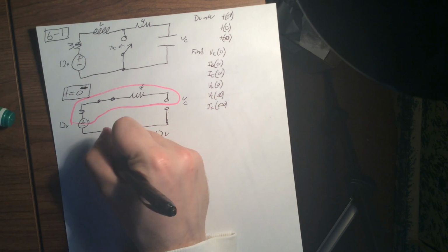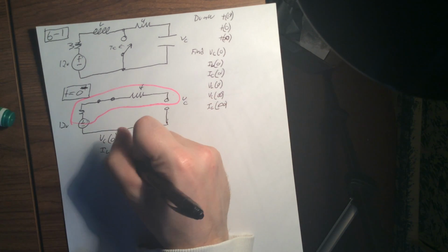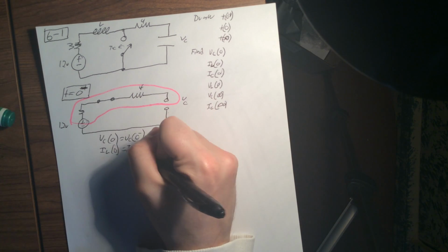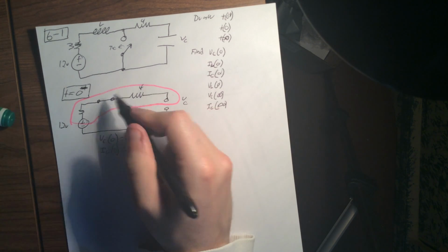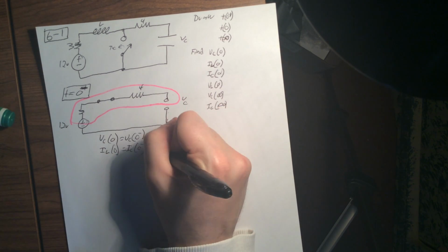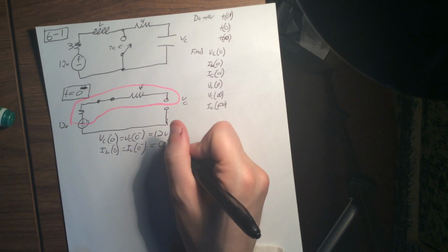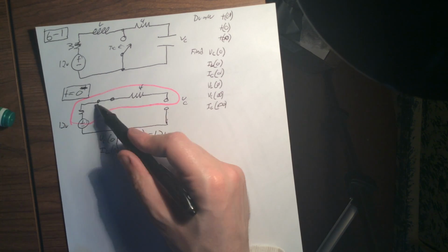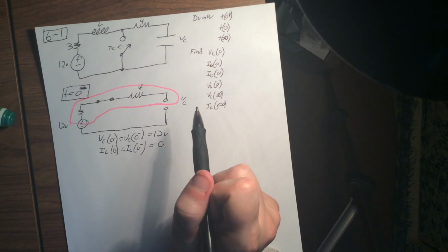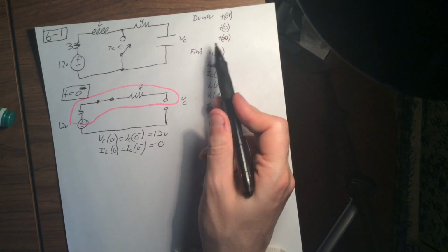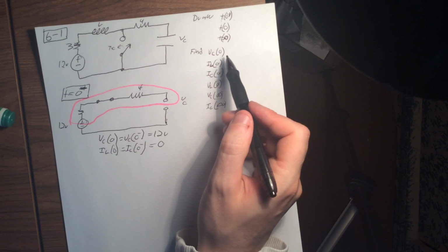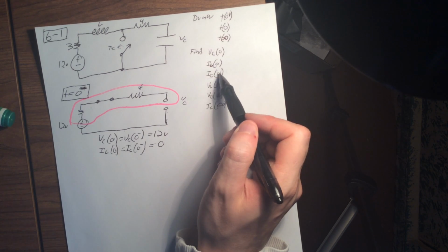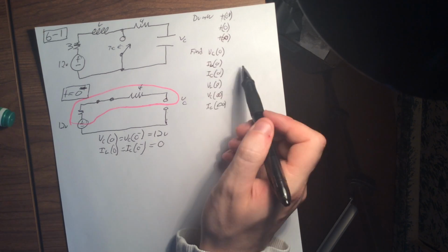Our inductor current IL at 0 is going to equal 0, coming up to 0 from this side. This is just a short circuit, so that's also going to equal 0 current going through there, because there's no current flowing through over here, so there's no current flowing through this. It's just a bunch of voltage holding together. So that draws out this one, and then we have our VC here, we have our IL here, and the current through our capacitor here is going to be 0, because there's no current.